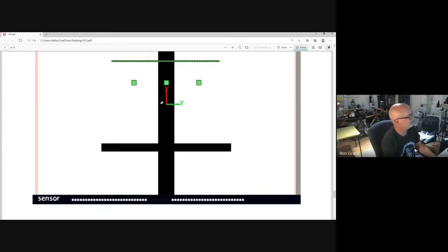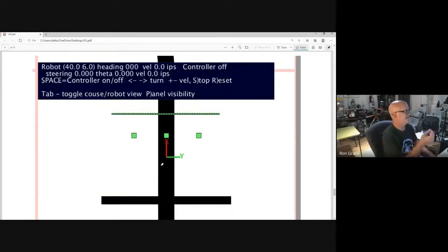I should note, when we're just setting up our robot, the size of the robot isn't taken into consideration for this differential drive robot because the only thing we're doing is driving at a given velocity and a given turn rate, and I'll illustrate that in a second. But the coordinate system you see here is centered on the robot, at this origin here. This is used for the positioning of our sensors.